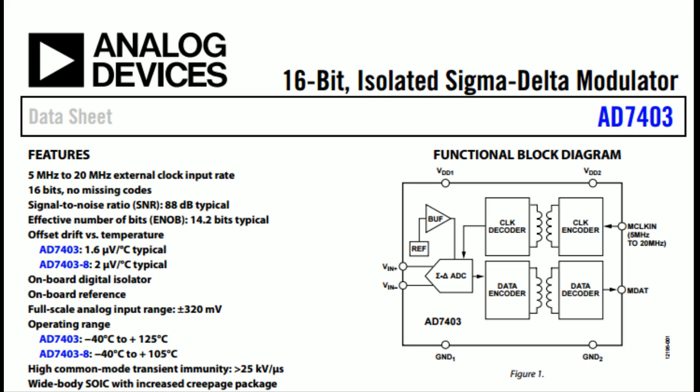In some cases you do it on the output. This one's done closer to the input. Say 1,000 volts got shorted to your analog input and you don't want it to get into the computer measuring it. This is typical of isolation. This is a good place to do isolation because there's only 2 bits we have to isolate. There's the clock, and there's versions of this where the clock is an output instead of an input. Same thing though, we just isolate 1 bit for the clock and 1 bit for the data. We don't have to do 16 or 24 bits for the data.